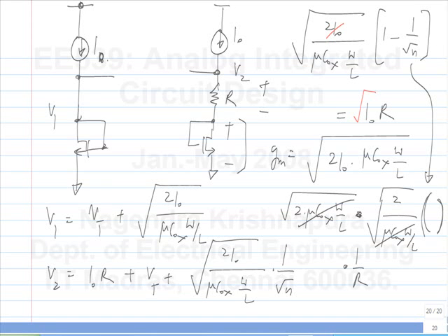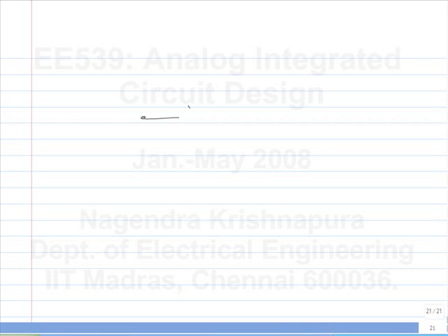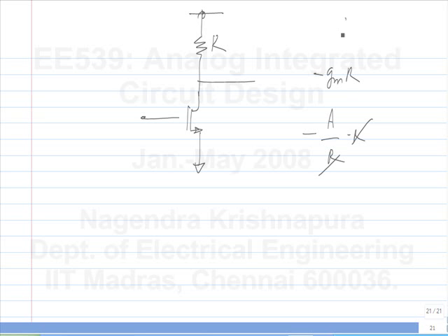Okay, this is again a useful circuit. Just to give you an idea of why it is useful, let's say you make an amplifier. What's the gain of this amplifier? Minus GM R. Okay. So if GM happens to be inversely proportional to this R or some similar type of R, then the gain will be some fixed quantity, right? If GM is some A by R times R, now GM will have temperature dependence, R will have temperature dependence and process variations, but you can keep the product of the two constant. That's the motivation for using some circuit like this. Okay. So it does turn out to be a useful circuit. So you can in fact try and get an accurate gain without using feedback. That's the key here, right?